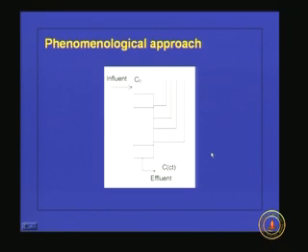See, this is the filter and we can have different manometers to measure the head loss at different points. The water is coming like this. Most of the time, especially in community water treatment plants, we use downward filtration. So, influent is coming and here there will be a constant water head available, and this is the filter media.